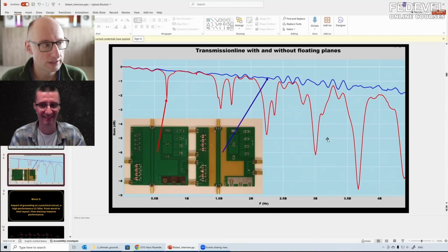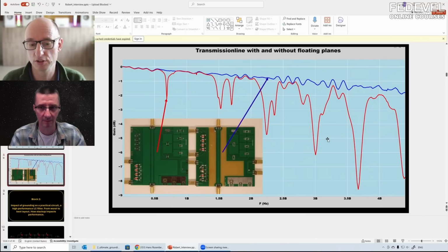I like it in a way because I very often like to get rid of heat, and this extra copper gets rid of a little bit of extra heat. But then you have to be careful that you ground it well enough, especially in the area of signal traces. If you have no signal traces in the area, then it doesn't matter because it won't get hit by a signal, so it won't form a standing wave either. However, I can imagine, I never did something like this, but if you're making a motherboard with 16 layers and you have 16 layers of loose copper and you have to make sure that's all connected, that would be total hell. So then I would say better not use that pour.